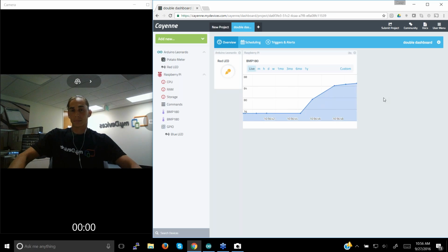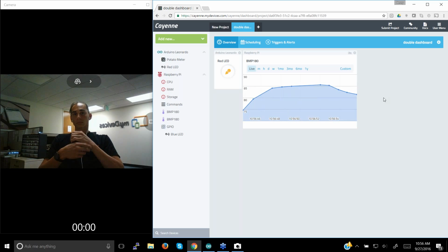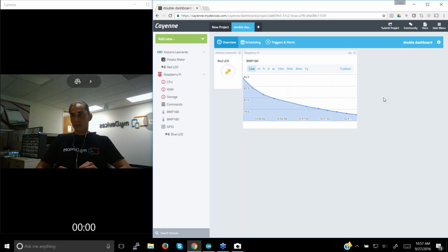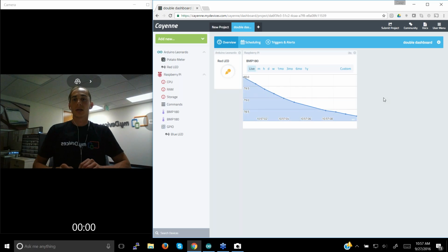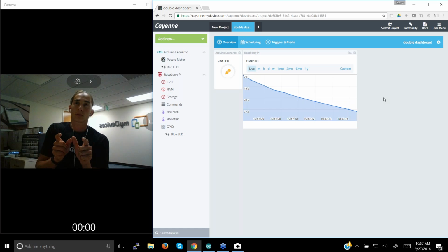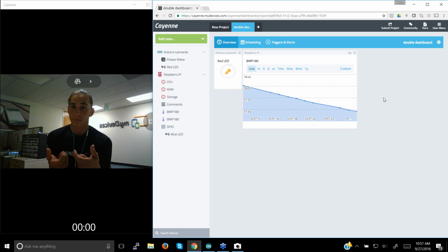This is another question about the two widgets. We had answered the first part, but he was wondering, can we use two custom values with the same source of data in the Arduino code and then use them as the data for separate widgets? Yes. You would send whatever data you're trying to get off of the Arduino to what we call a virtual pin.